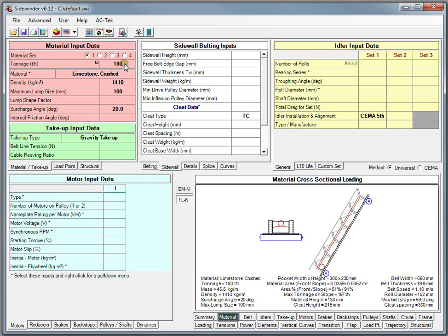Quite often you'll look over here, and say we were going 200 tons per hour when we ran this, we'd say, oh, look, we're already 102%. We're flooded over this maximum profile here. So typically we probably will not want that much more than that.